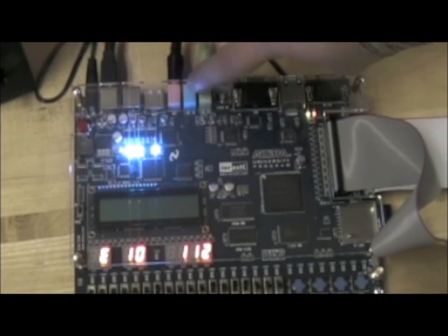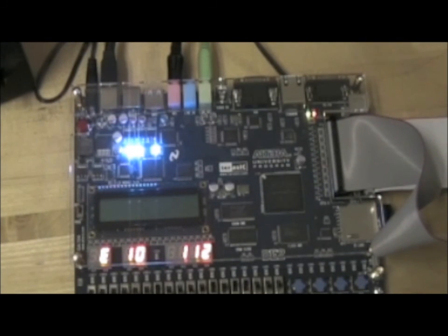We have a codec here that we're using. It receives the information from the other FPGA, from the MP3 decoder, in an I2S format, and basically streams it in that format to the codec, which then outputs it through the line out to the speakers. The codec also has a microphone capability where it can actually add the microphone output to the speakers. So that's what we're using for the karaoke.